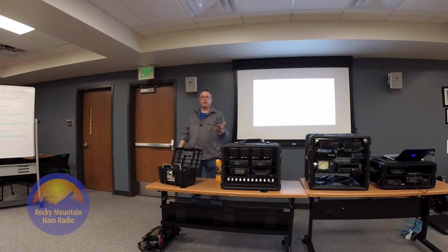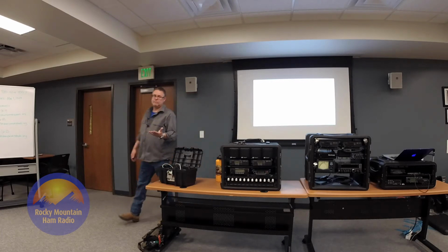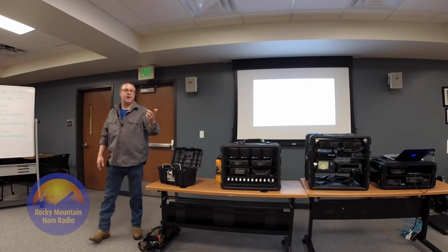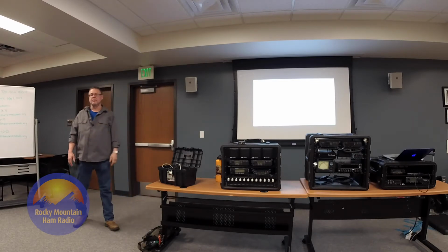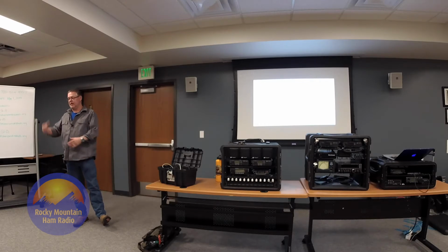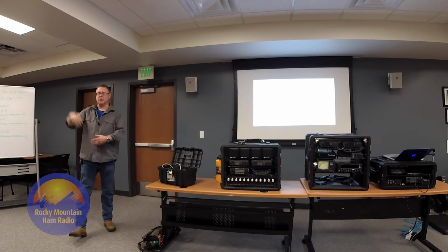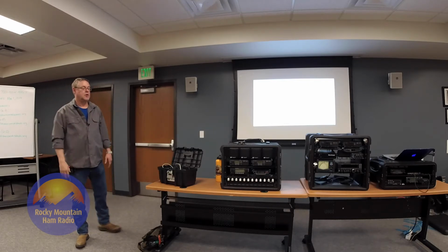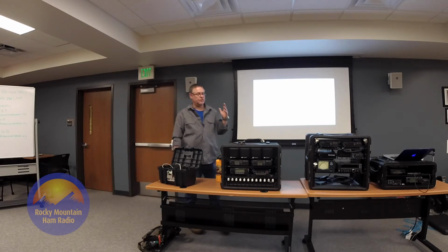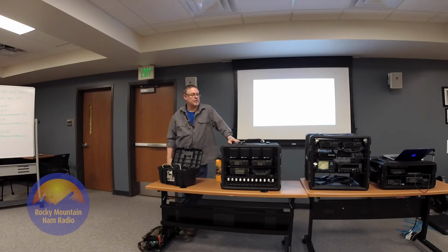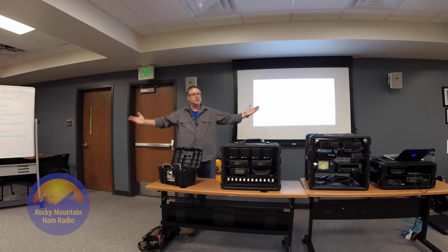The next thing is you're going to have a pack of coax and an antenna tripod. If you get some of these MFJ tripods or military tripods, there's several other people that make them, that have the pole that goes out the middle and is adjustable, whether it goes up 20 feet or up 6 feet, it doesn't matter. Carry one for your antenna. Even if you just take it out the front door and stick it out on the grass, it's 6, 7 feet up and it's in the clear and not inside the metal building. This building's built of metal.